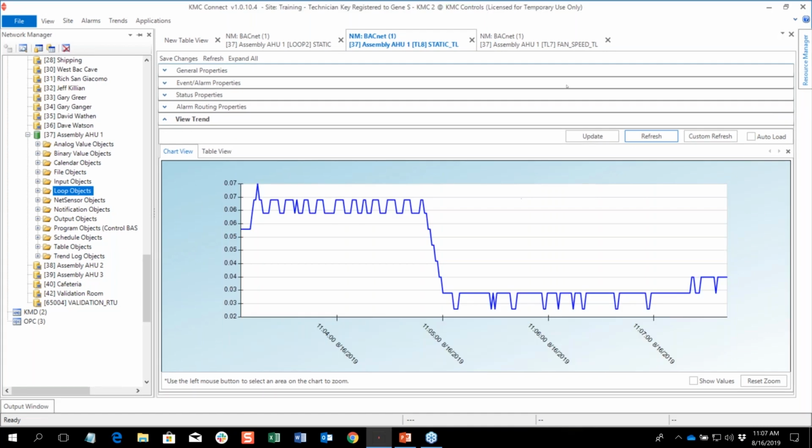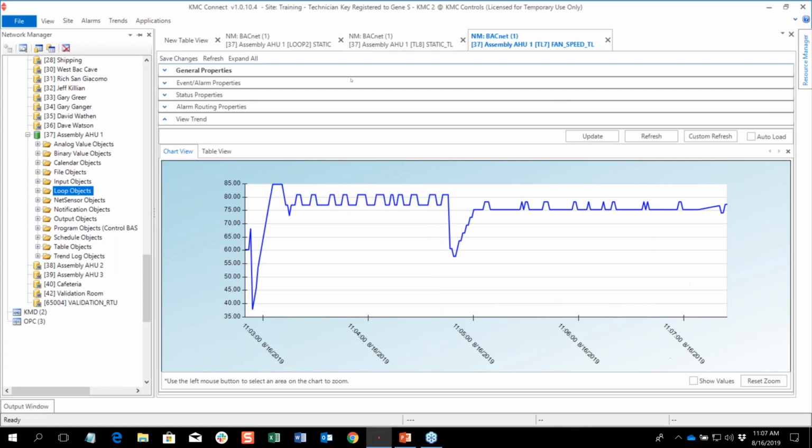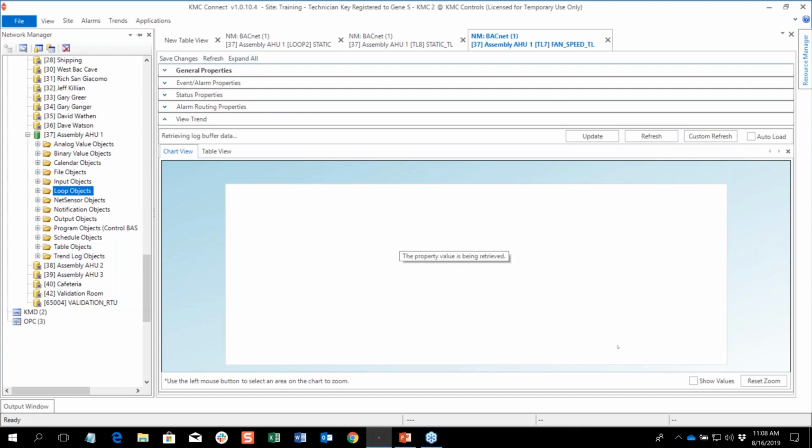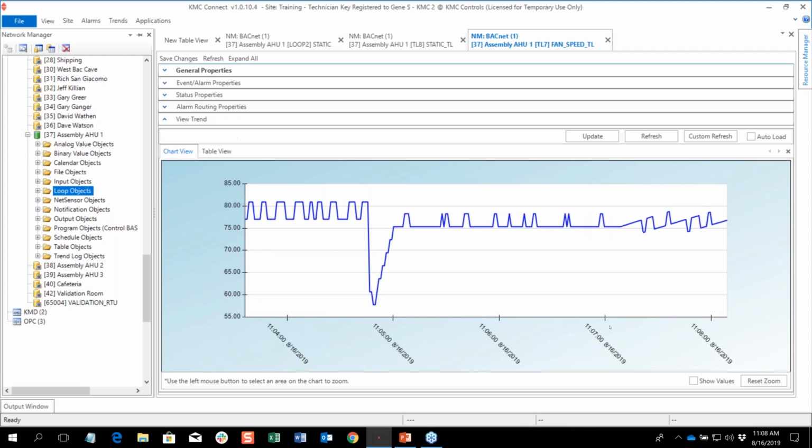But I'm always going to have that error between set point and what my input is. If I didn't, you'd see that loop output go back down and I'd be steady at 0. But given a condition of proportional only, I'm always going to have steady state error because it always takes error to create a proportional output.